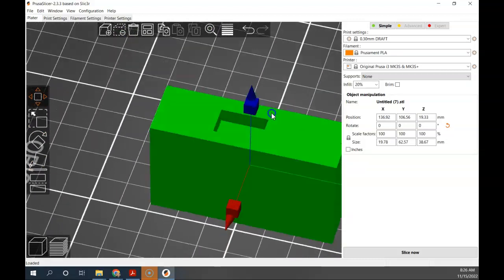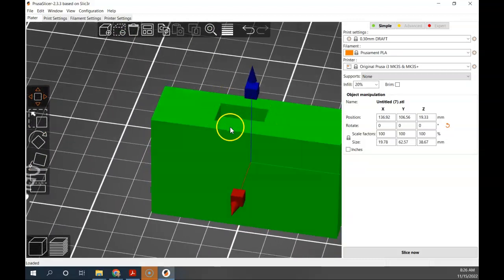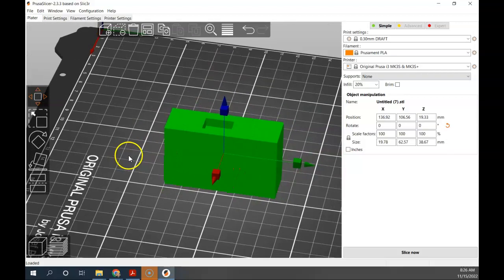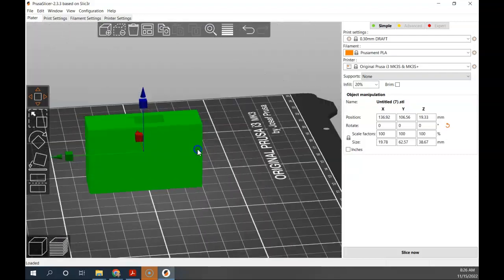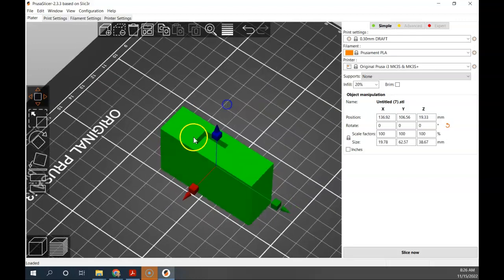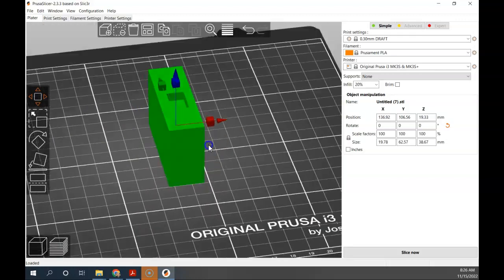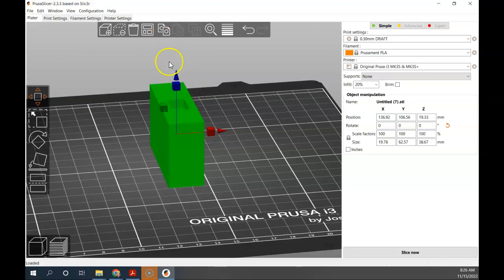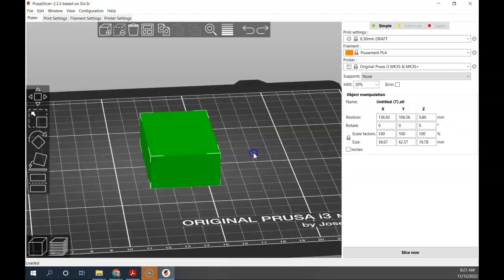Notice that's exactly the same shape, and because now this little indentation is facing upwards like a pool, I could print layer, layer, layer, layer, layer, layer, and I don't have to worry about any kind of overhangs. So sometimes the overhangs can be taken care of just by reorienting or rotating your shape so that the printer doesn't have to fight gravity there, essentially. We're working with gravity instead of against it. That's my first suggestion, is to pick a good direction. But sometimes it's just not possible.